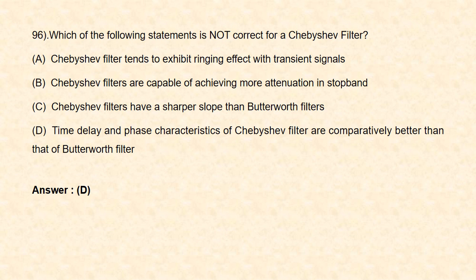Third statement. Chebyshev filters have a sharper slope than Butterworth filters. This statement is also correct. Time delay and phase characteristics of Chebyshev filter are comparatively better than that of Butterworth filter. This statement is wrong. So option D is the correct answer.